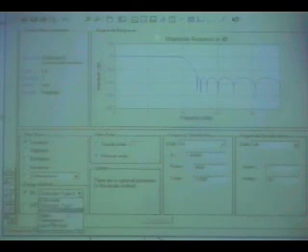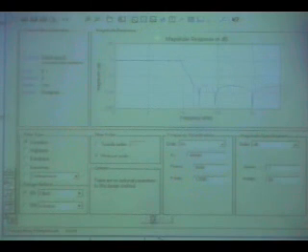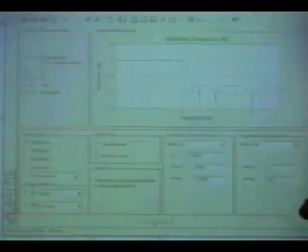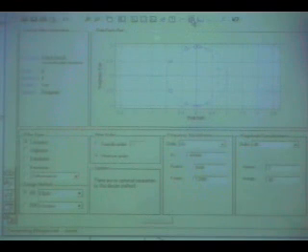But then you say give me elliptic, okay, elliptic filter, and you say design. 8. The same filter, instead of 31 coefficients, but now there are ripples. You can see there are some ripples here and ripples here. 8 means 8 poles. You can go look at the pole zero plot as well, but we have already seen this, 8 poles, 8 zeros. So this is an elliptic filter.